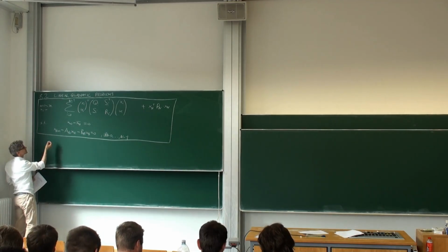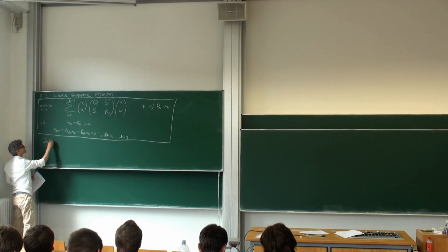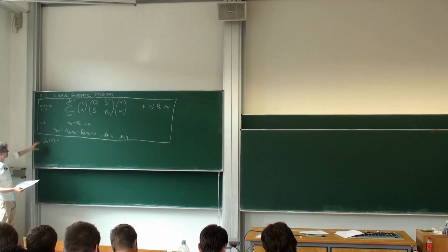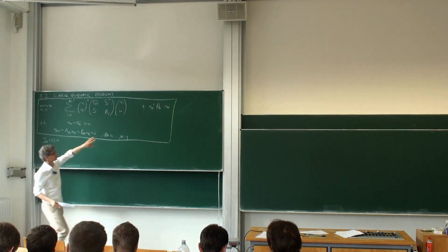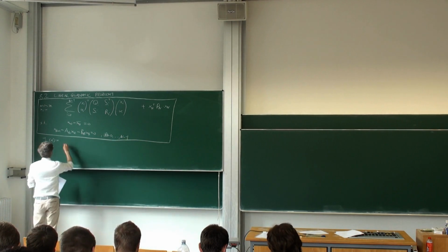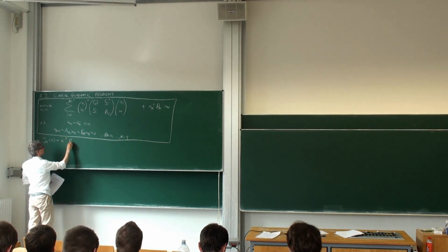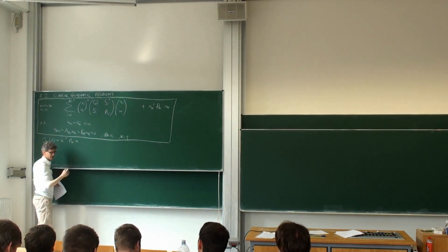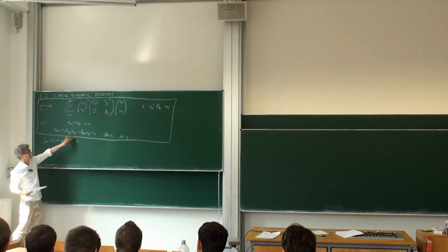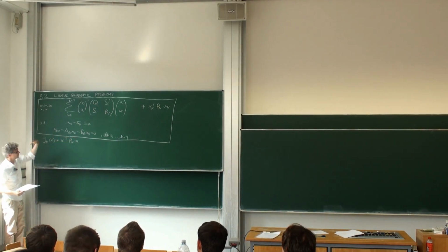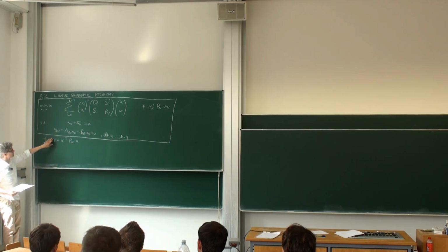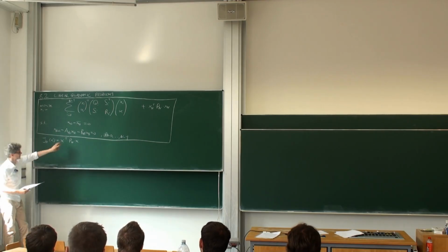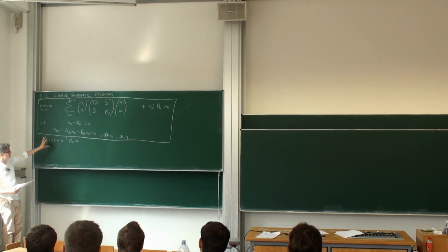The first thing is what will be J_N of x. The cost to go at the very end is, of course, the terminal cost, which is this thing here. So it will be x transpose P_N x. So it will be a quadratic function. And the good thing about quadratic functions is I can characterize them by a matrix. I need to just store the matrix elements and then I know everything about this quadratic function. So I don't need to go through all states in a state grid or something. I can just know this is the matrix and now I know how to compute that.